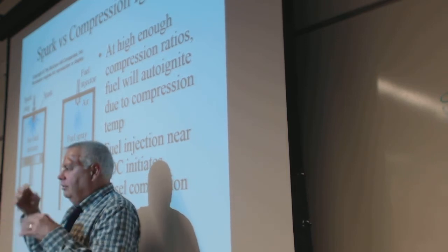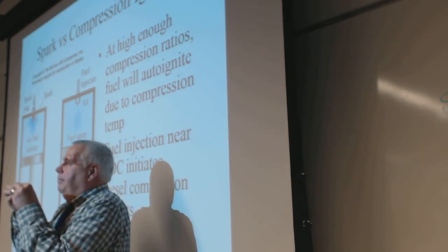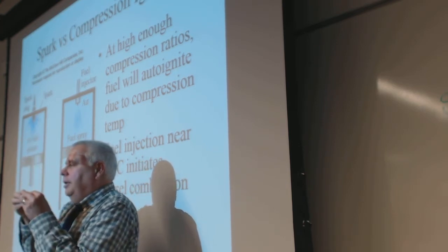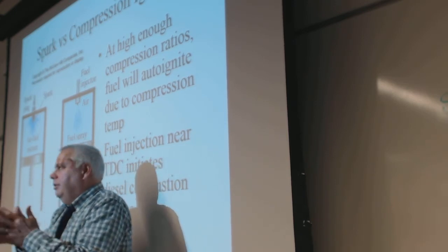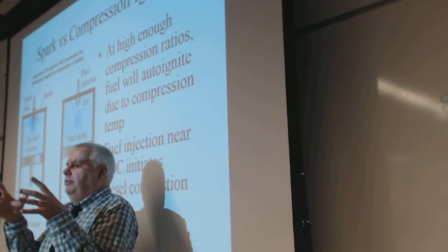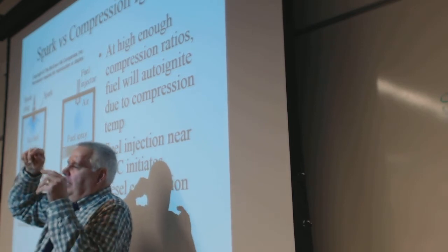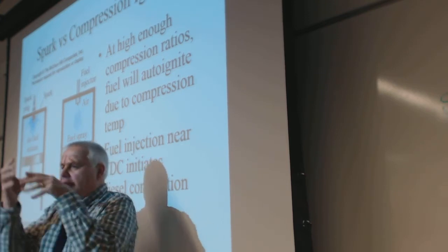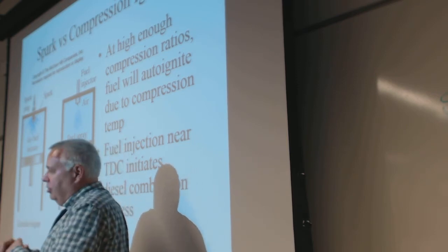If you ever hear the diesel rattle, there's sort of this pre-ignition phase, and then, I forget what to call that. But basically, when there's enough fuel-air mixture that it will burn, enough air to burn the fuel, that one will pop. And then the next thing that happens is mixing-controlled combustion, where as the rest of the air mixes with fuel that's unburned, then it burns. And they burn relatively slowly after the pop. Gasoline burns faster.